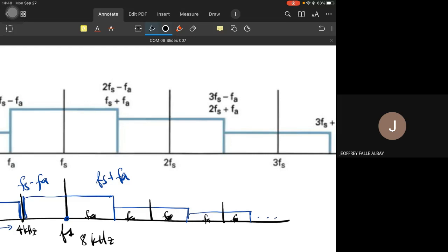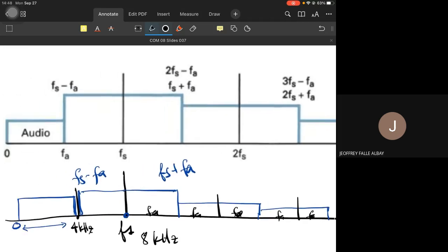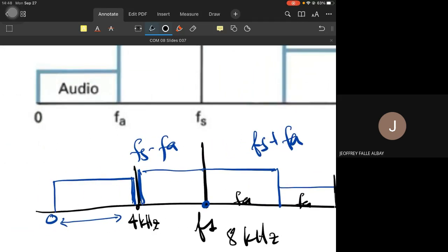Or for a definite value in this example, 4K, 4K each. So that is the range, or half the bandwidth of each harmonic of the output signal. But let's focus here, okay? Focus here. If indeed the sampling rate is twice the frequency of the input signal, they will not overlap.